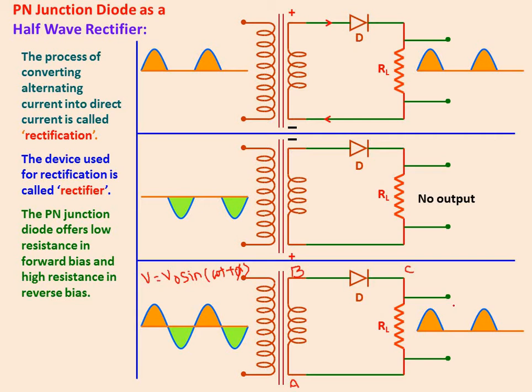The current flows through the diode during positive half cycles only here, and current flows through the RL only in one direction. You can notice here, only through the positive half cycles alone. Hence, we can say a half wave rectifier gives discontinuous pulses, DC pulses, in only one direction. There is no other direction. That's why I am calling it directly DC.